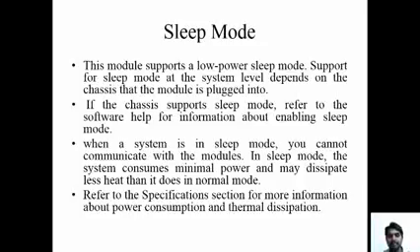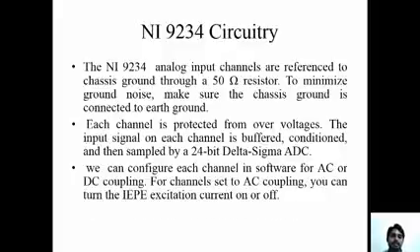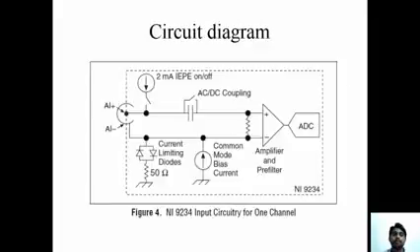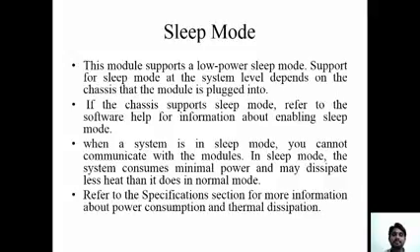Next, each channel can also be configured in software for AC or DC coupling. For a channel set to AC coupling, you can turn the IEPE excitation current on or off. I already explained that IEPE is the piezoelectric sensor interface that is maintained by the software, as shown in the circuit diagram.